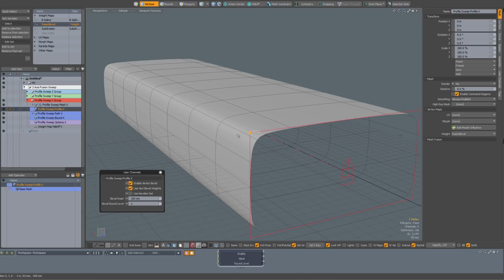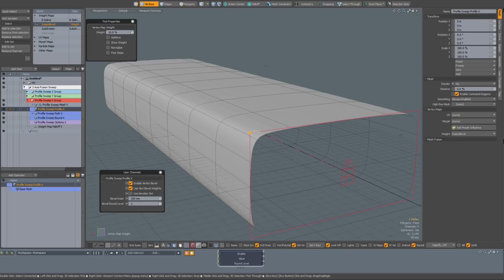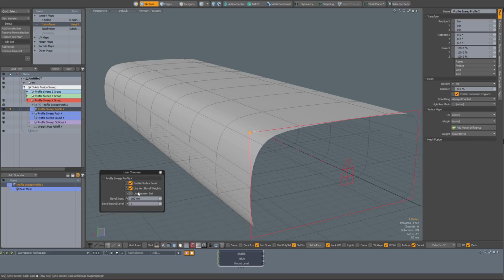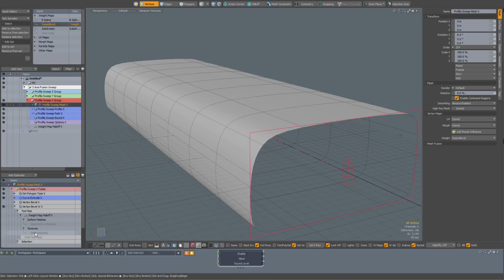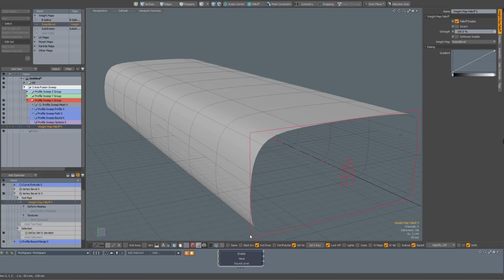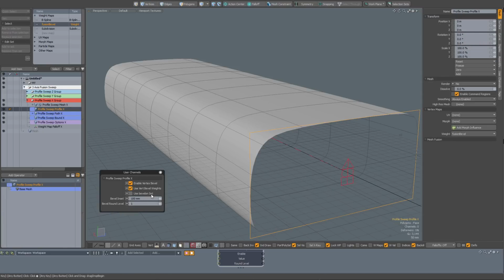So if I press Shift W to activate my vertex map weight tool, when I click and drag in the viewport, you can see that I can adjust the weights of that bevel, because when use vert bevel weights is checked, as said earlier, when I go to my procedural, it is the vertex bevel WX which gets activated, and that operates through a weight map falloff. The weight map has been set to that Fusion bevel, and it also works on the selection set, but that is not active right now. Use bevel on set has been turned off.